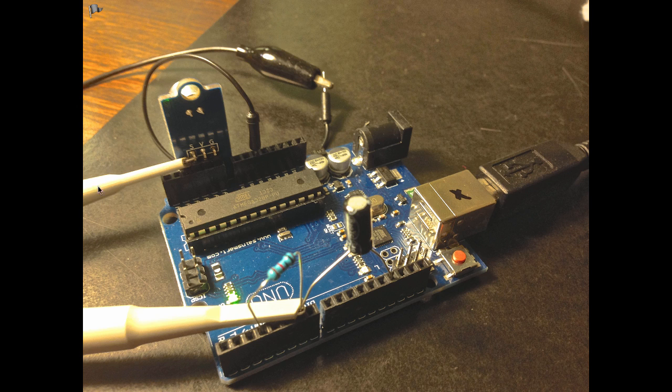What you also see are 2 oscilloscope probes hooked up, this here to the reference voltage and this here to the microphone voltage. When I demonstrate the sketch in action later on, then we will see this here as the yellow trace and this here as the blue trace on the oscilloscope. So you can see how this signal occasionally goes higher than the reference voltage, and then the interrupt service routine is triggered and we get a report of the event on the serial port. This here is the ground connection to the oscilloscope.